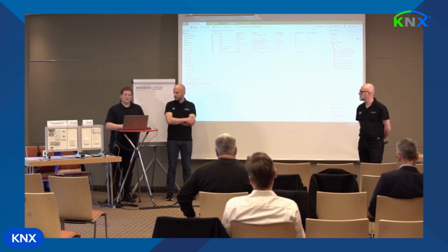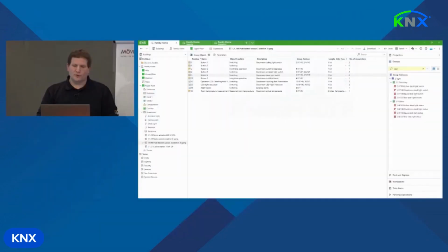And in order to do this in ETS, there's a concept which is replacing the currently known dummy devices. So in order to do this group address assignment to visualization tools in the past, you placed dummy devices with dummy objects and did dummy associations to these dummy objects with their different dummy sizes. This helped in creating the filter tables correctly for the couplers. In the future, this will be needed to be known as trusted sender, and therefore we extended this concept. So if I go to the topology,